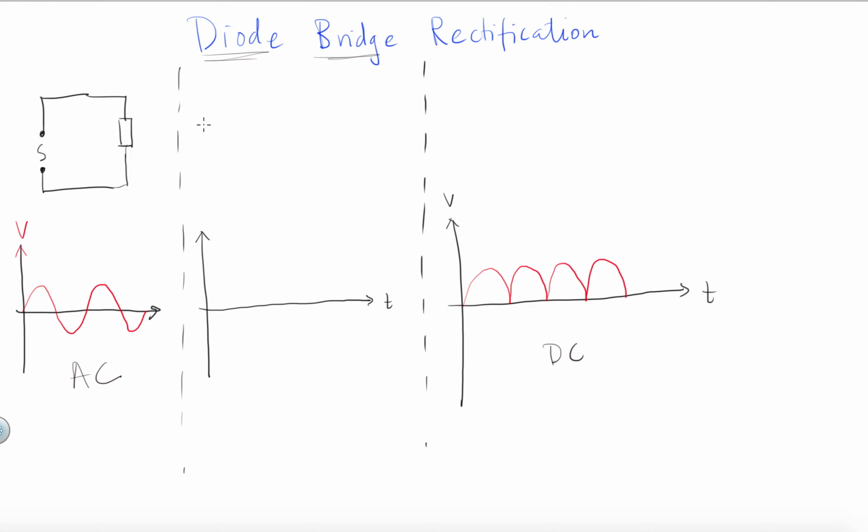only by half, and we do that by, here's our AC source, here's a wire, we plug in series something called a diode, then we have our resistor, and we're measuring the voltage across the resistor, by the way, and then we connect up to the AC source in. What the diode does is it only lets current flow in the direction of the arrow.